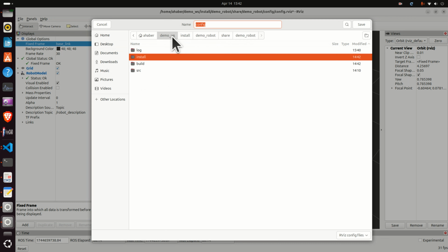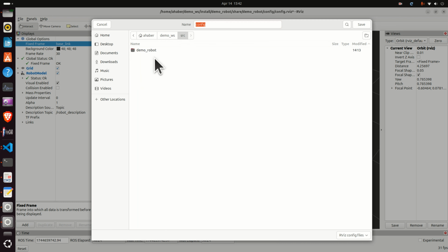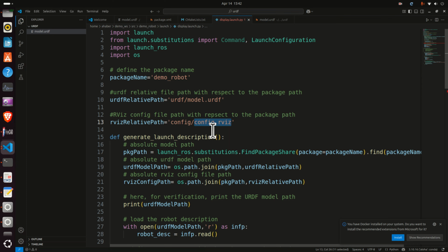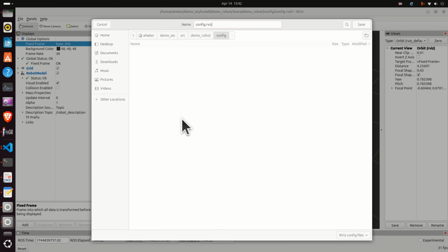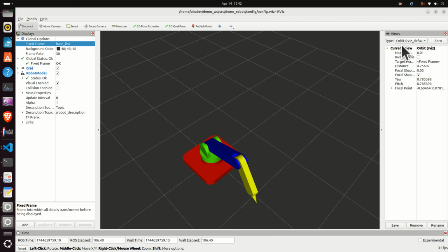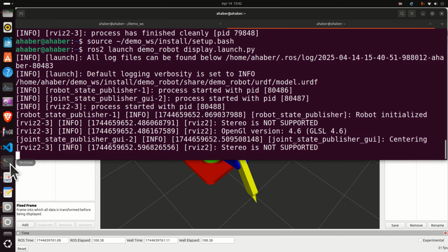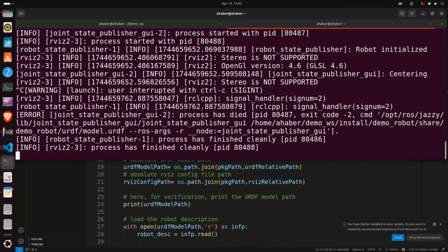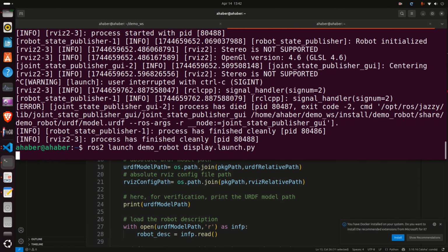So let me now go back. You should go back to the demo workspace. That is the original workspace. Then go to the source, then go to the package, and then find the configuration folder, and then I'm going to save it as config.rviz. Know that this file should precisely match this file name in your launch file. Save it, and let's close everything by going to the terminal, pressing Ctrl+C, and now if you run again, magic will happen, and everything should...